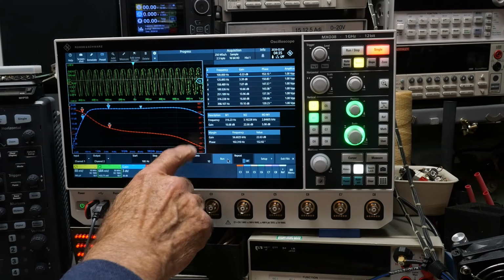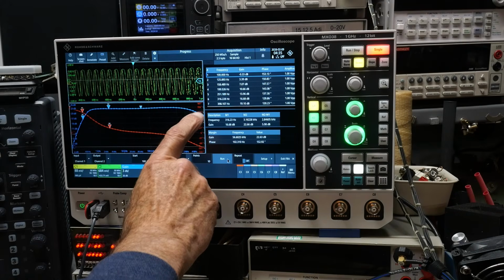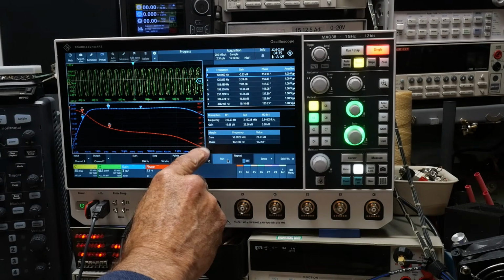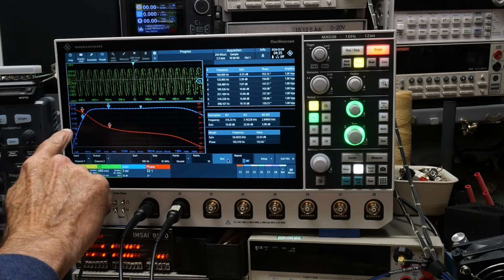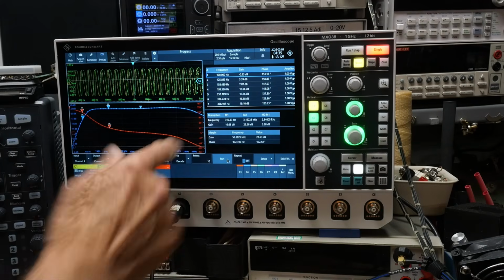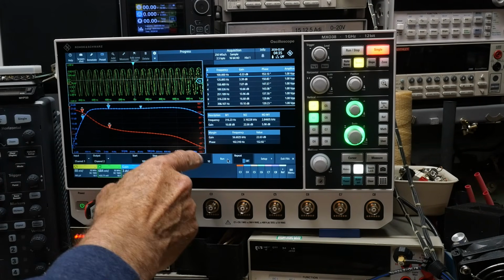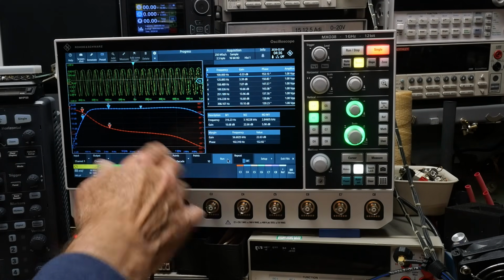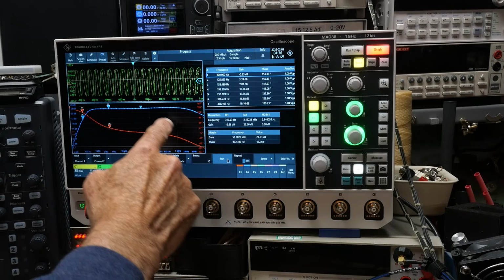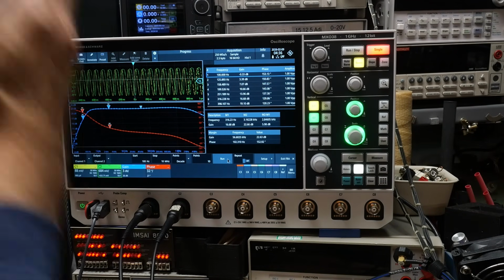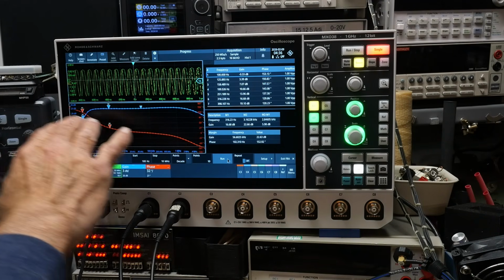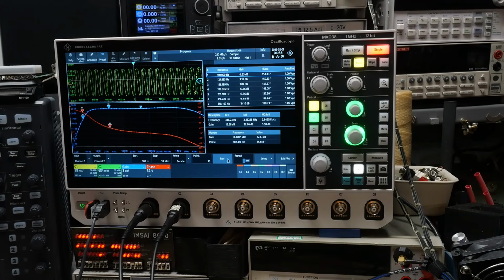Currently, it started at a positive 155 degrees of phase, and it went down to a minus 100 degrees of phase, okay? Had it started in the middle, it would have gone down until it ran out of space, all right? And it's got to go somewhere. There's no place for it to go, so it starts up at the top again and then continues on its merry way. So sometimes you'll see that big break in the center that is not anything funny going on. It's still nice and smooth. It's just that particular graph couldn't fit it all at the same time, all right?